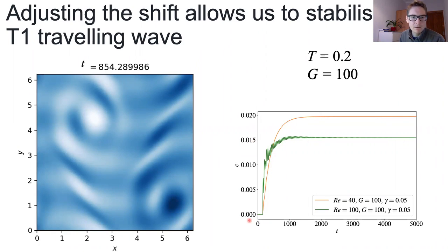So there's an open question about how good my method is if you start off your initial shifts a very long way from the corresponding phase speed that you're looking for. But certainly a naive guess of 0 gets you the traveling speed in this case. It's ongoing work to determine how robust that is in terms of the starting value and the target traveling wave. And it works up to Reynolds number 100, as you can see here, where you're fairly turbulent.